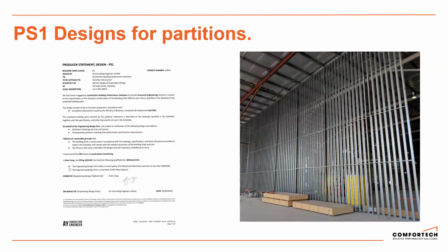So we don't see an awful lot of PS1 designs for partitions. Generally, it's ceiling related. There is a benefit of getting a PS1 for your partitions as part of that package. The main reason for doing it is that the engineer can allow in their partition design to take the seismic loading. They know exactly what it is.